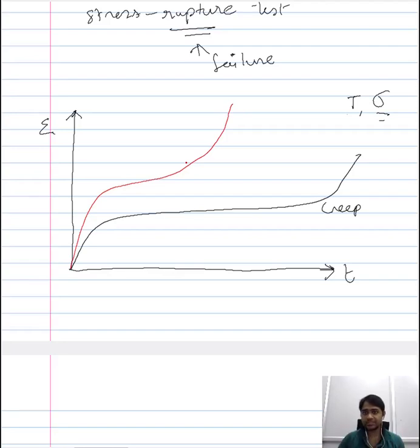This is because we have already seen that with increase in stress, irrespective of the creep mechanism that is operational, the steady state strain rate increases proportionately with respect to stress. Usually this increase is in the form of a power law, wherein the n could be equal to 1 or 5 depending on the dominant creep mechanism. Irrespective of it, there is a proportional increase in the creep rate with increase in the stress, and that is the reason why you see a curve like this, and this point here is essential because this is where the material fails, or the failure of the material.